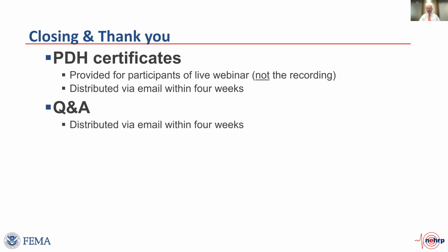That was the idea. For high-rise construction, so very tall construction, there is much to be gained from considering the dynamic response of the system. And so there still are triggers for modal analysis for high-rise construction, for tall structures, because that dynamic character is quite different from the simple characteristics identified in ELF. So I'm not trying to suggest that all systems should be designed with ELF, but you should know that if you design a short building using the modal response spectrum analysis method, there may be behaviors that you don't pick up because it's a linear analysis, and ELF would have covered a lot of those problems.